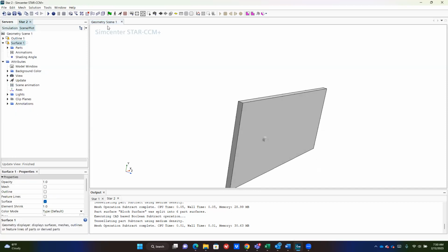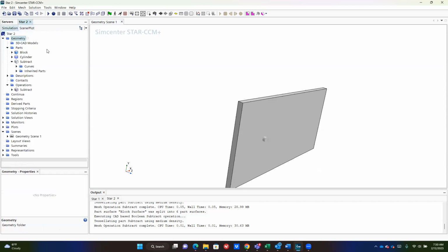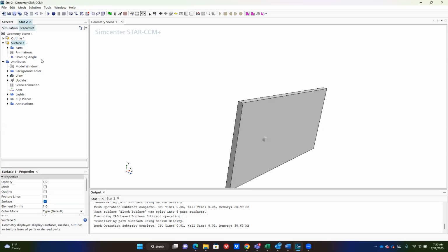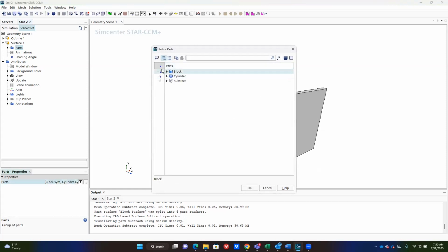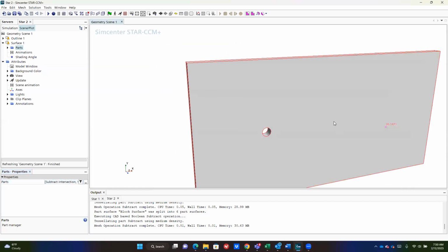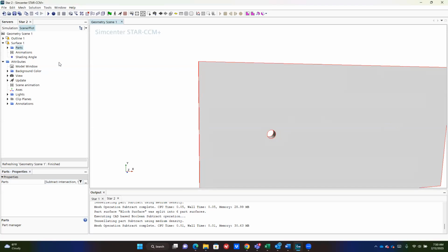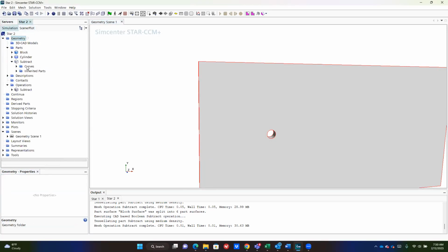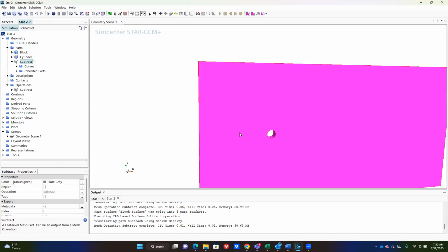So you can operate between this geometry scene on this tab, or the actual simulation settings here. So when I'm on the scene settings, I could go into the surface, click on this, and unclick everything and focus on this surface of interest. And here's our fluid domain. Okay. So when we come here, we can see we had the outer domain and the cookie cutter cut out.